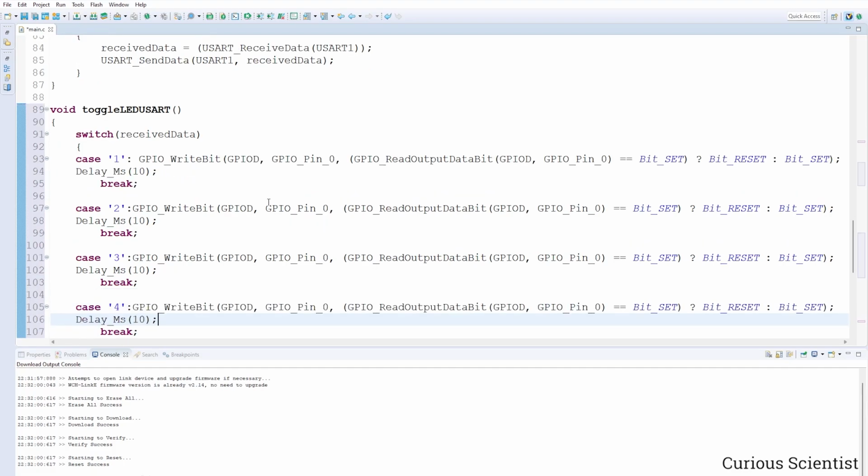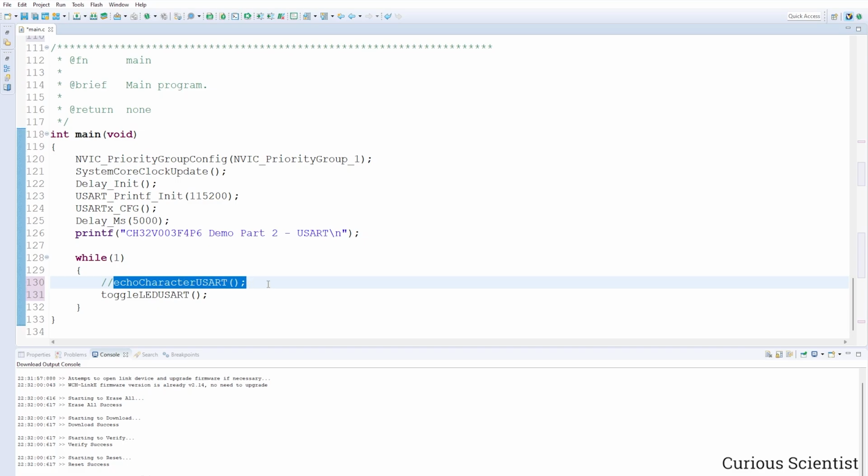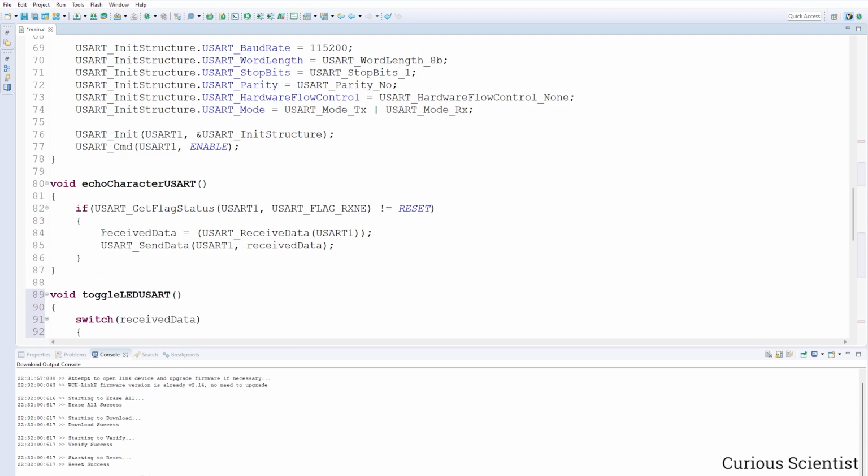And then we agreed that we have a GPIO C1. So let me do that. And we have a GPIO D2 and GPIO D3. So that's fine. And now this function should go here because it should kind of poll the USART. However, when I removed this function, I also removed the part here where we pass the character received from the USART port to the received data function.